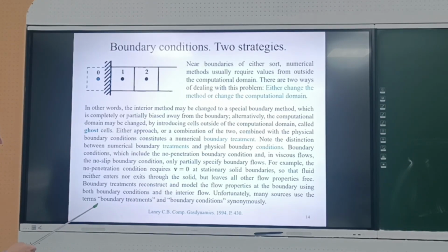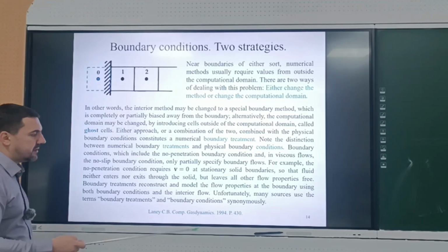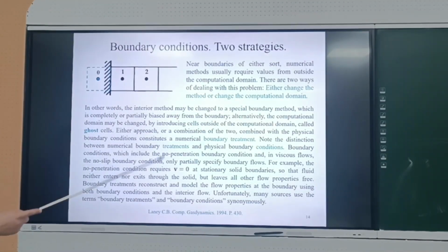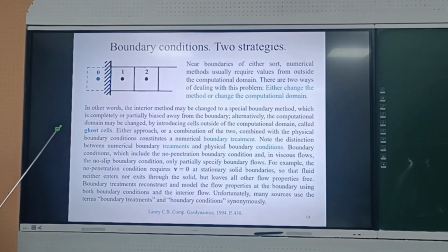Boundary treatments reconstruct and model the flow properties at the boundary using both boundary conditions and the interior flow. Unfortunately, many sources use the terms boundary treatments and boundary conditions synonymously. Okay, so the most important idea here is that it is possible to use different numerical implementations of your physical boundary conditions. We will follow the idea of ghost cells.